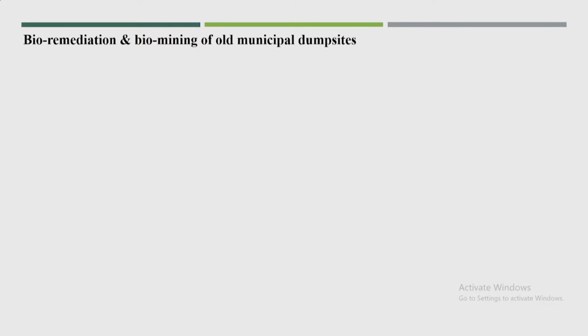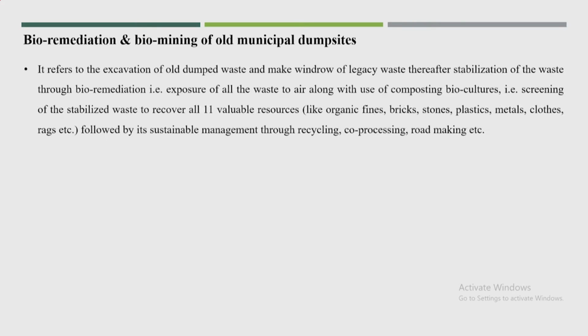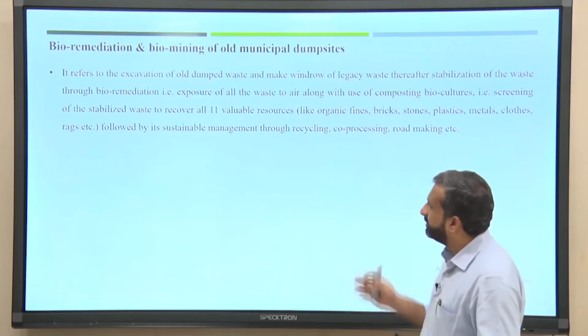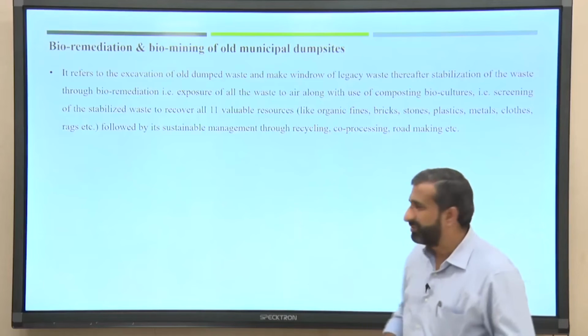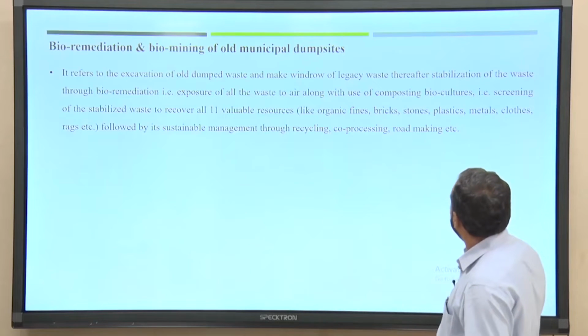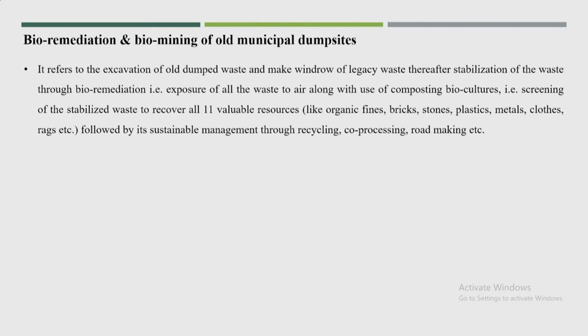So, what do we understand by bioremediation or biomining of old dump sites? It refers to the excavation of old dumped waste. When you say bioremediation or biomining, especially the word biomining, it refers to excavation of old dump site waste and making windrows of legacy waste. Remember windrows from when we talked about windrow composting. So, make a similar kind of windrow. Thereafter, stabilization of the waste through bioremediation.